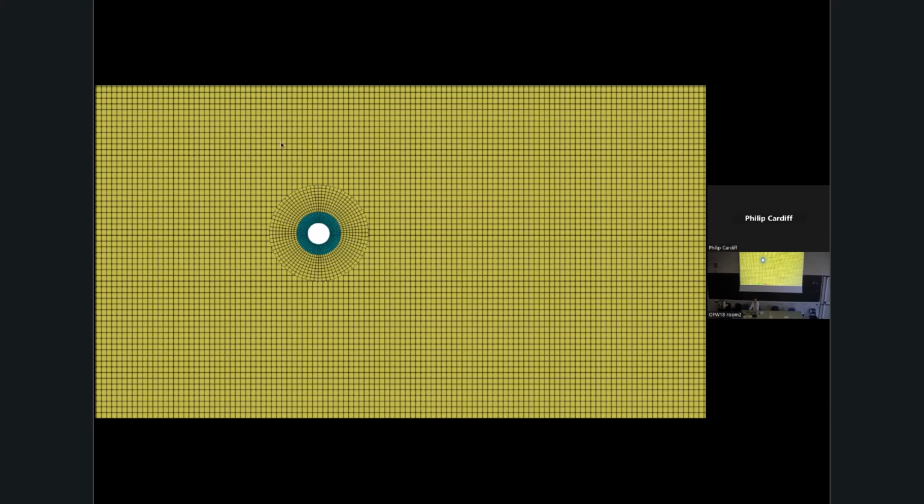There is an example for that overset solver where you have the fluid domain in yellow, and flow around a rigid cylinder. I think the cylinder is moving in some way. But in this case, I created a torus of deformable material, kind of rubber, inside that, so it's no longer rigid. Instead of prescribing a mesh motion on the rigid cylinder, I prescribe it on the inside of this deformable cylinder, so I'd expect that to deform.